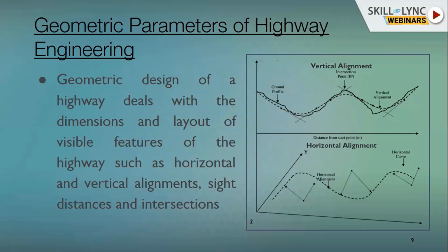If we are designing an expressway which has a broader radius, and if you are designing a village road or a major district road which has not that much bigger radius, we need to try to squeeze in 2-3 radii to make it a sharp turn. So it purely depends on the classification of the roads we are designing. That all again comes back to the codes which we are using. Different types of road classification, as I mentioned earlier, have different sets of code values. I would show the different radii to be used in further slides.